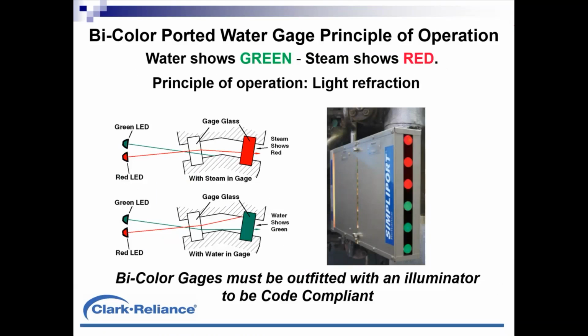If you go back 15 plus years ago, LEDs were not in the marketplace on these gauges, and there used to be halogen incandescent lamps used and red and green glass filters. Now on modern lighting systems, these are all LED. So if any of you in the audience today have any of the old time designs, you might want to consider updating those and getting rid of the old unreliable illumination and updating to LED. The LEDs are going to provide 10 to 15 years of normal service life and minimize your maintenance and reduce power consumption.